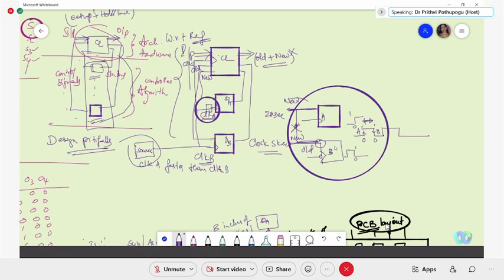This is regarding the triggering, but the distance between A and B will also give you two different instances of input sensitization. If this is 8 inches, and this is 8 plus some 4 more inches, so this is 8 inches and this is say 12 inches, this introduces 1 nanosecond of extra delay.